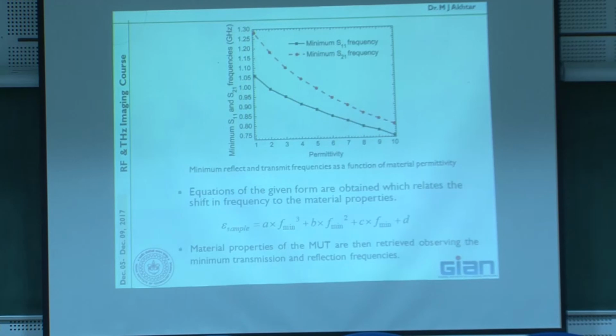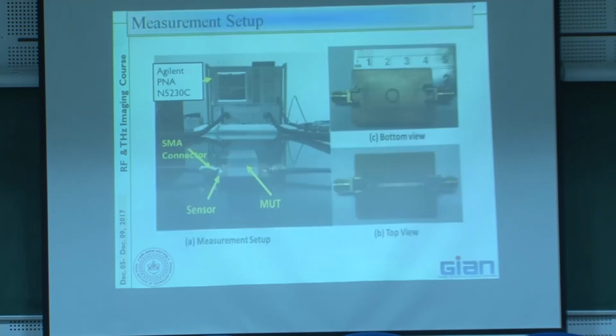So this is again the same, you can get an equation, also an equation of the second order, third order, that also works fine. It just shows how you do it practically. So you have designed your sensor, microstrip, bottom side, put this side here, put bottom on top, and then you measure the shift in frequency. Okay, this is how you do it. This was for normal characterization, and this works. So size is compact, you can use many materials, it's very simple. Just put on top, nothing to do, and it works quite fine.